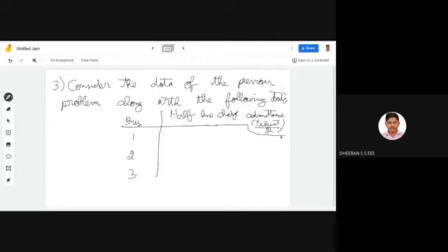So I have already told, whenever you are considering your medium transmission line and your longer transmission line, you have to consider the factor of your y shunt by 2. Because most of the lines will be in a pi type model. So in the pi type model you have to consider your y shunt by 2 value.